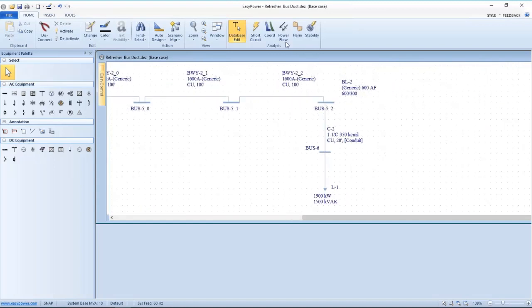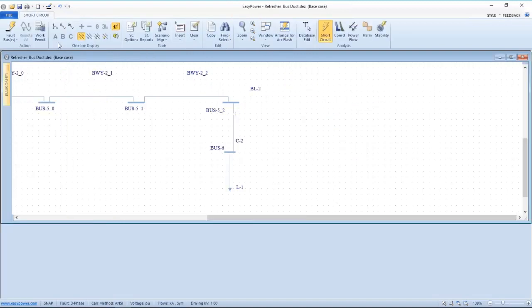And in either case, what do I want to put here? I want to put a breaker. In this case, I'm using a 600 frame and a 300 amp molded case circuit breaker. I still have very good protection as far as operator safety at the loads, but I need to really caution folks about exercising any switchgear up here that's next to the hazard, next to the bus duct itself.